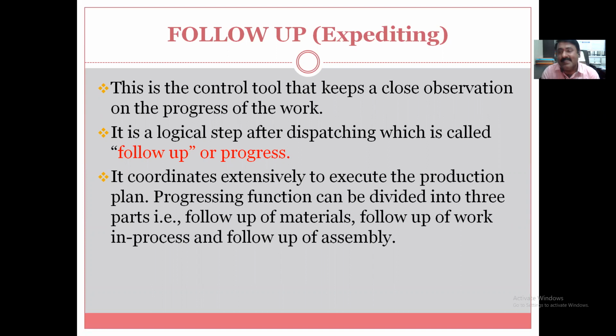Now, after analyzing, you will come to know that maximum 2 can be increased. We will go up to 42. After 42, we cannot go for a single product more within a shift, and you are running only one shift. So the step required is to go for some overtime for the remaining 8 items, every day 2 hours extra working, or to go for some rescheduling so that 50 items can be produced, utilizing more manpower and machines, and checking that the material is available for that 50. Okay, material is there, if we have planned for 50, we can go for it.